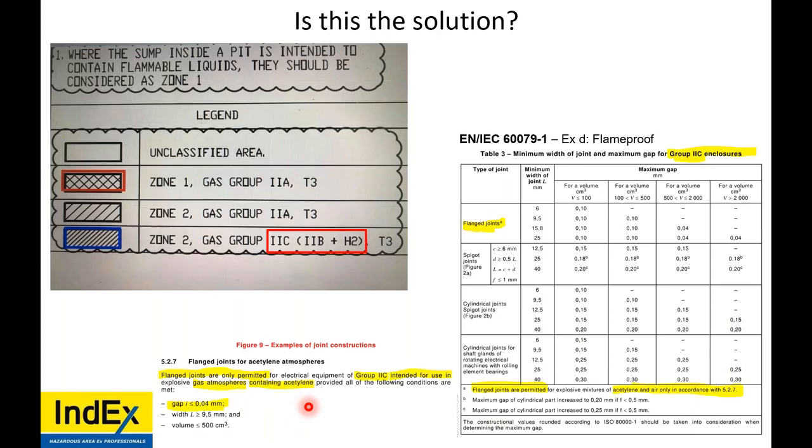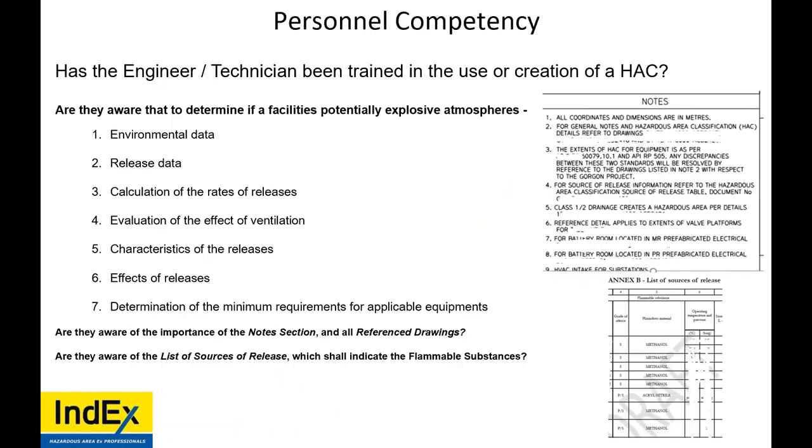That is why you will not have a hinged type flange Ex d 2C. It's too tight a tolerance to guarantee with a hinge. We're talking very finite measurements.